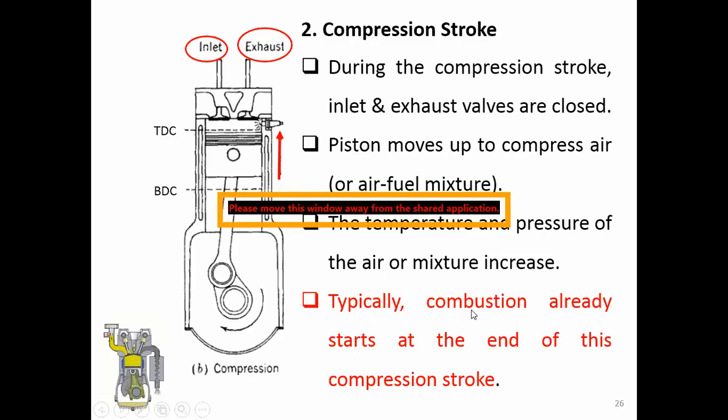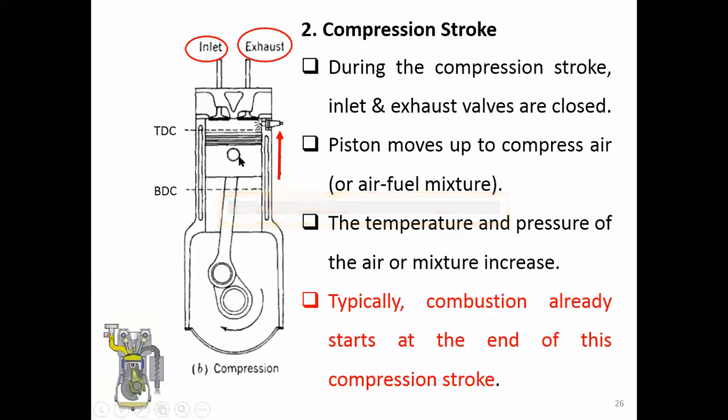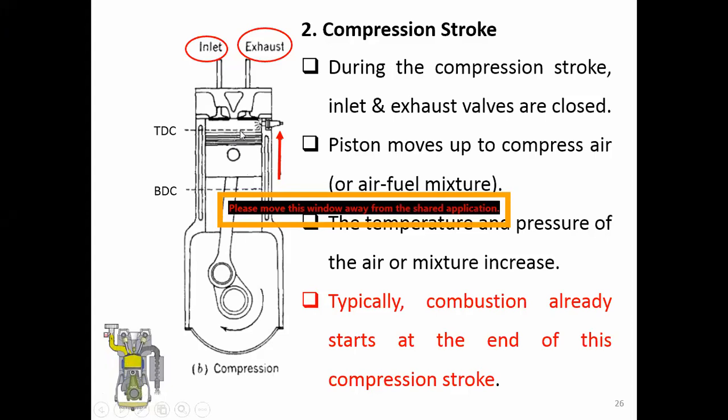Theoretically, when you learn thermodynamics, we always let the combustion start at the end of the compression stroke. But in the actual cycle, the combustion always starts a little bit before the end of the compression stroke.